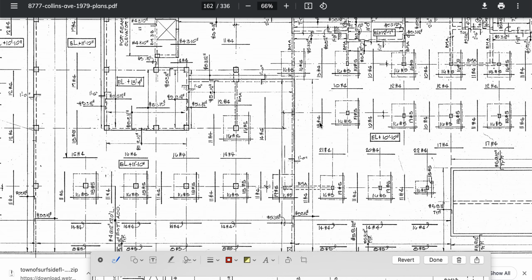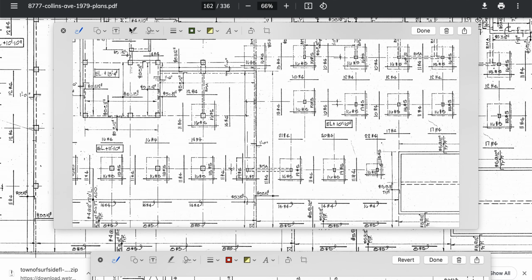So they would go from here to, well, wait a minute, there's no column for it to meet here. So then the main bars would have to go from here to here, some main steel, to make this steel go over to here, to support on top of this steel. It then would allow this steel to span to this steel, to transfer the load to this steel, that would transfer the load from this steel to this column and this column. You see how complicated that gets because of the way they did this? This is my last part of it, it would look like this. Let's see if I can get you unscrewed from what I screwed you on.